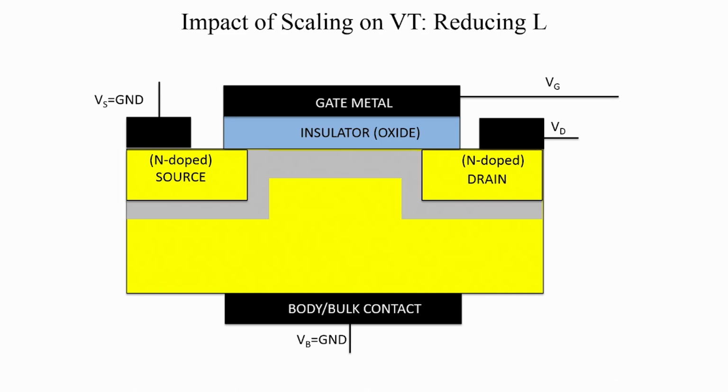So, we have the threshold voltage, and what does the threshold voltage depend on? Once again let me repeat, it has got these 3 milestones. You need to first get your flat band voltage, which you now know depends on phi ms plus any trapped charge in the insulator. Okay.